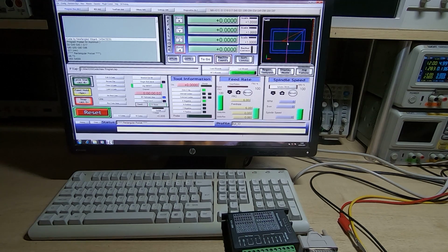This is a very simple test file I've created just to allow me to make this video. When we now run this program, I won't do it of course, this is not attached to an actual mill, but when we try and run the program now, all the motion will use the G54 offset, which is what we've just zeroed. If we go back to machine coordinates, notice there is now something completely different. This is really how far we are in the X, Y and Z axis from the machine's home location. But the G code will now use this as the starting point for all its movements.